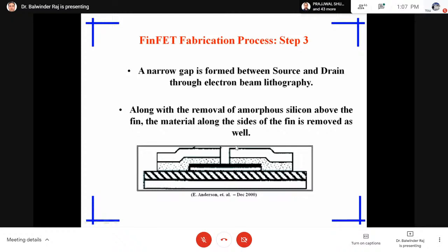So why is precise control of this cut required? Because, as we previously mentioned, there is an overlapped structure, and sometimes an underlapped structure is also there. So if the whole material is not removed, if the dose given of this HF chemical that we have to add is slightly less than required, then that will be under-etched and under the gate structure.